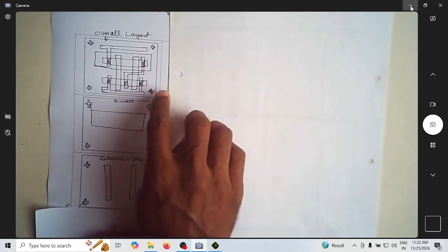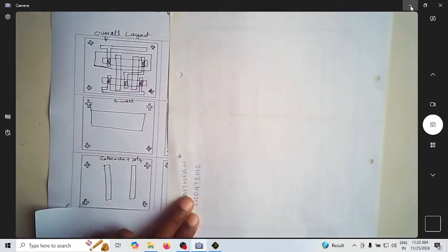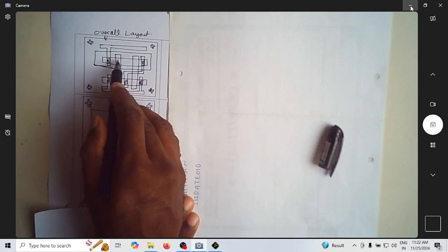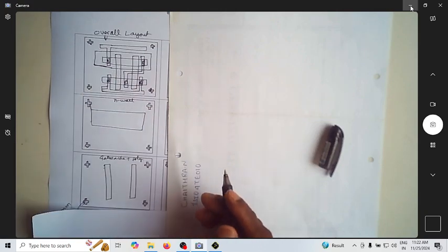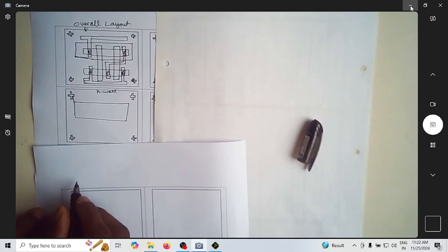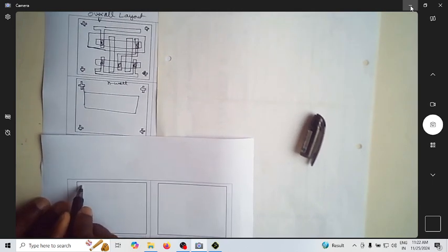For the gate oxide, you can do one more mask, where you define the gate oxide only in this region. Only here you have your gate oxide. Maybe I can write where the gate oxide mask will come. For the gate oxide mask, I have to have an alignment mark which is identical, at the same point, for all the masks, something like this.